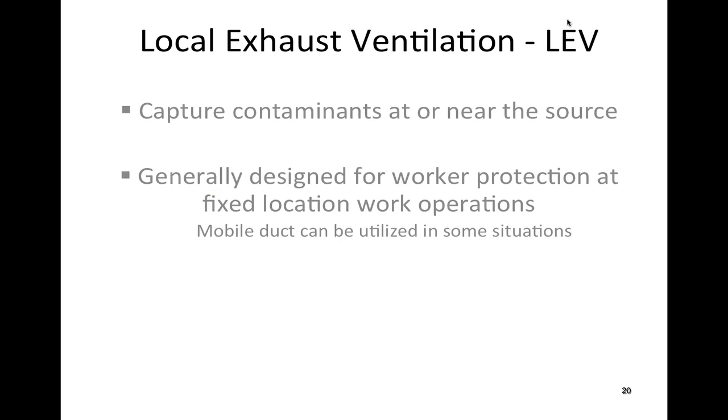Okay, so some of the issues we're going to wind up with is that the turbulence that we were talking about, the friction from the sides of the ductwork, is going to influence these things, because we have a fan in this system, but we may have a long run of ductwork. We may have turns in this ductwork. We may have a certain geometry to our hood. We have filters in there and so on and so forth. All these various devices increase friction or slow down the air movement. They affect the air movement.